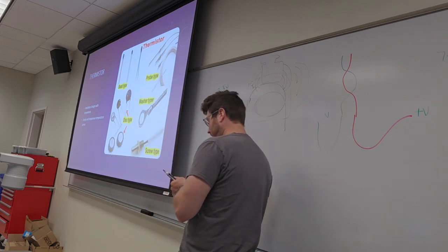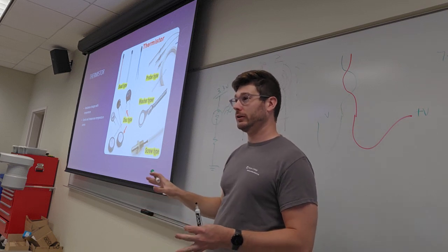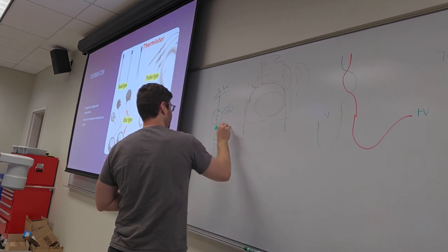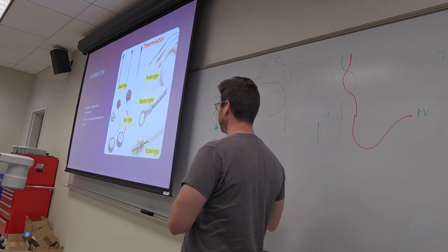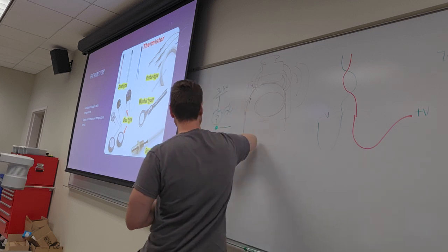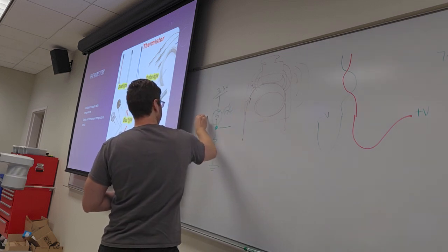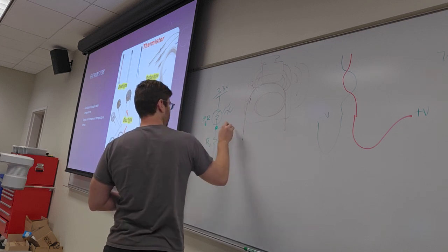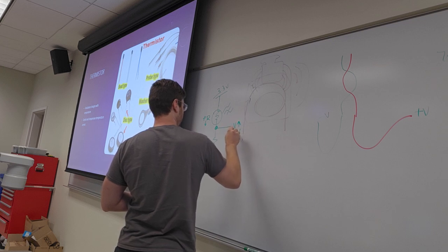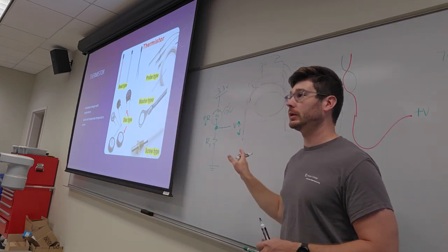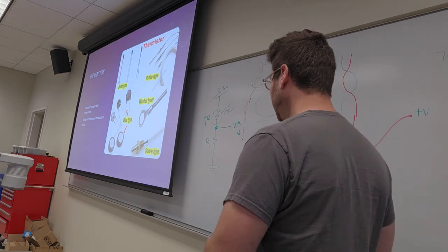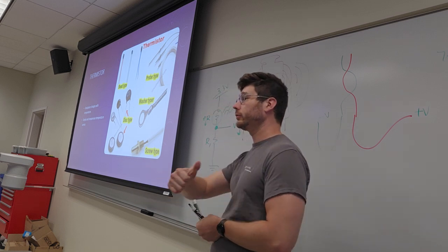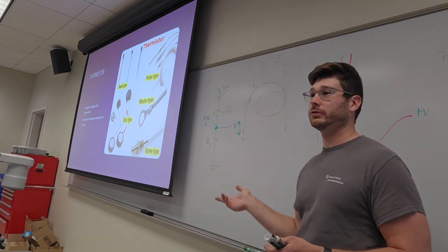This is getting into the weeds, the circuitry of it all for electrical engineers and such. But if you understand this, with our voltage divider here, we can get voltage from our resistance. This is a voltage divider, a potential divider: if this voltage is stable and this one goes up or down, this voltage will go up and down as well in an efficient, measurable and repeatable way. Nice and simple, literally 2 resistors, 2 jelly bean parts, and a thermistor could plug right into a PLC.